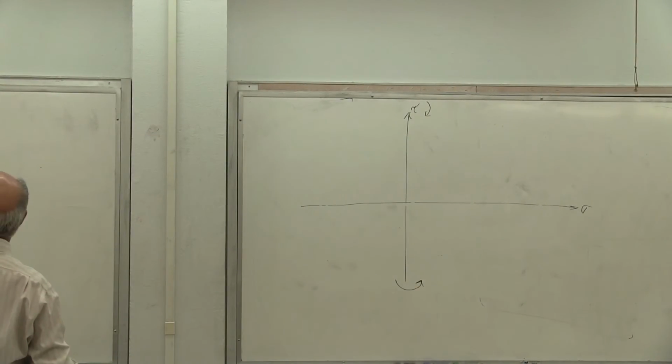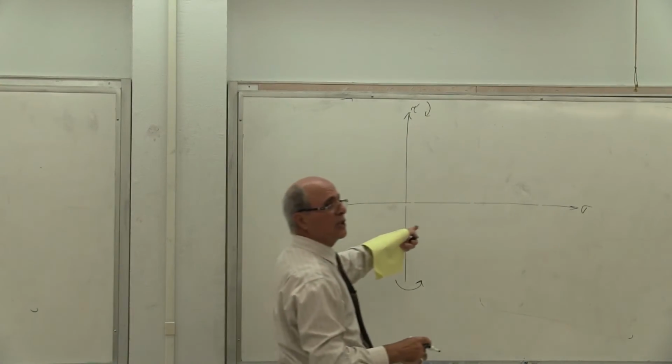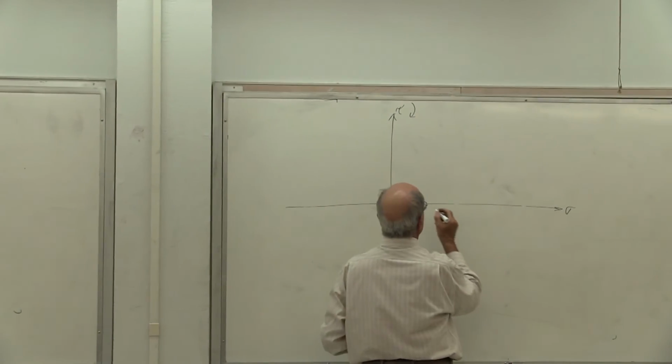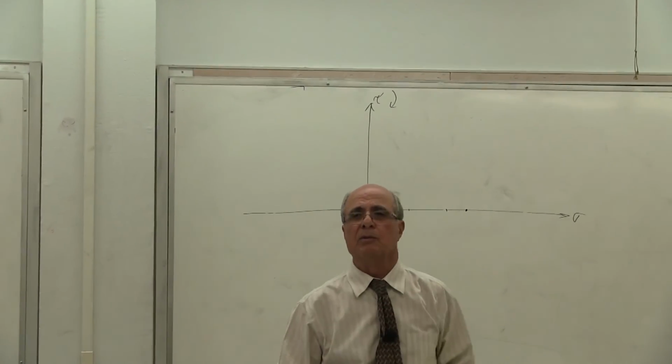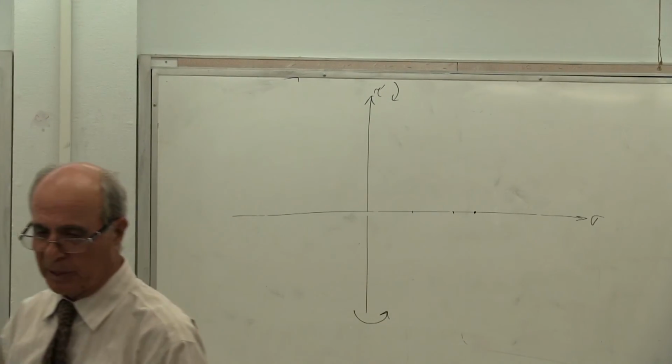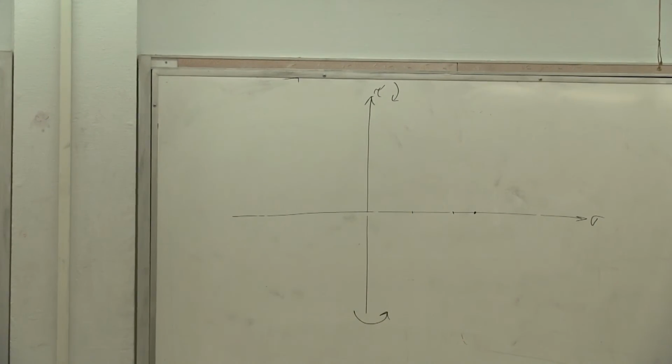X plane. X plane has how much sigma? Look at it. You go 5, 10, 12.3, yes or no? So you go by a scale, 12.3 on the sigma side, yes? Now comes to the shear. Now this is the key here. The shear for us is negative